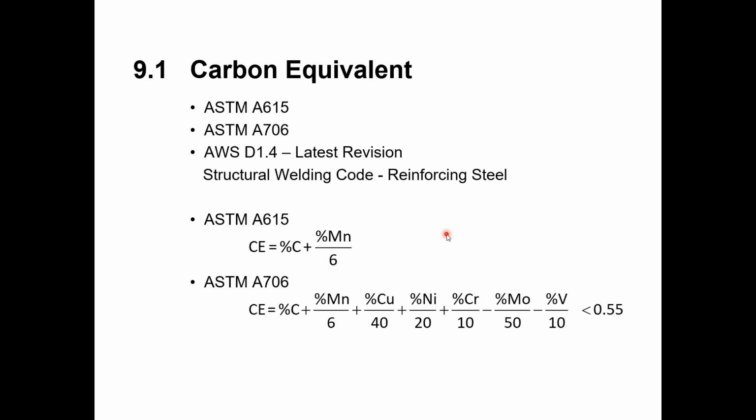One thing I'll say here, because I always get this question, what about tack welding? It's in the name. Tack welding is welding. And so the same heat, the same thermal input is being applied to that steel. So whether you're tack welding it or welding a 24-inch long bead, there's still an opportunity that you might embrittle that steel. So tack welding is welding, and the same procedures apply that would apply to any other kind of welding.